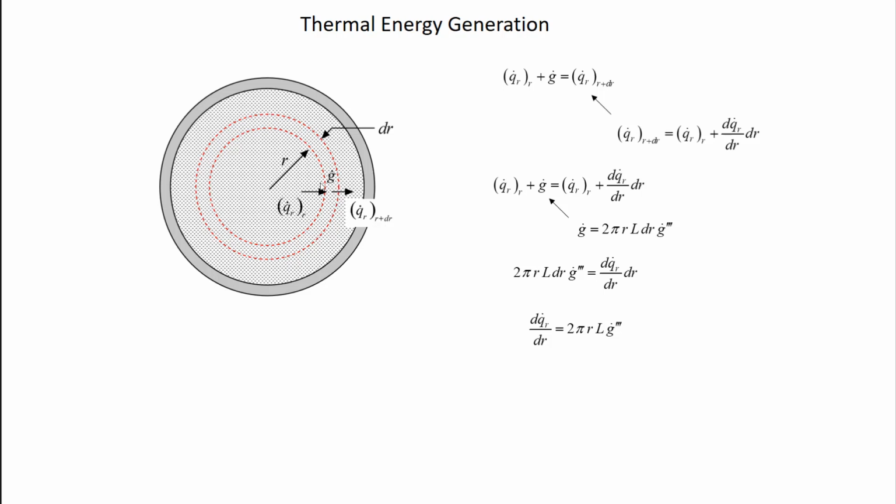And then I can't forget about the fact that my control volume includes inside of it a bunch of hay that is undergoing a volumetric rate of generation. So there's going to be another in to my energy balance, and that's the thermal energy that's generated within that control volume, right? So that'll be G dot. And this G dot has units of watts, right? These are all energies, so these all are, I guess, energy rates, so these all have units of watts. This is watts of heat transfer through this surface.